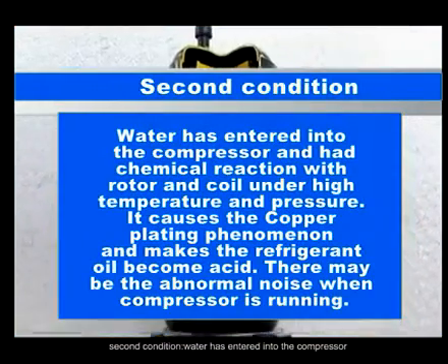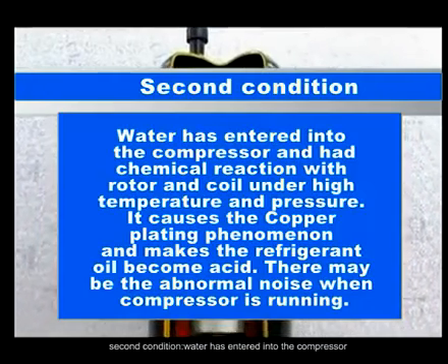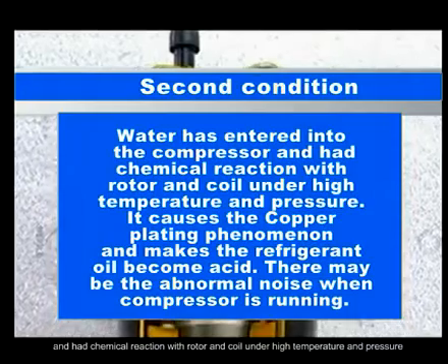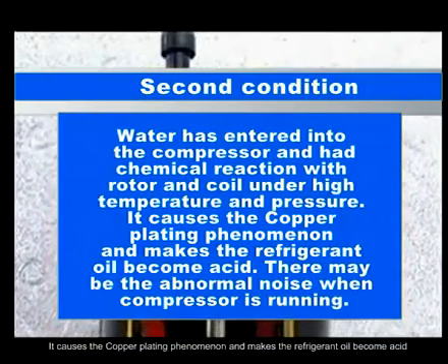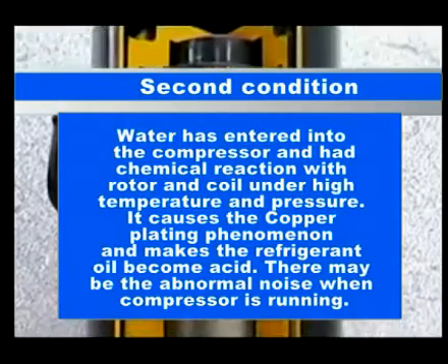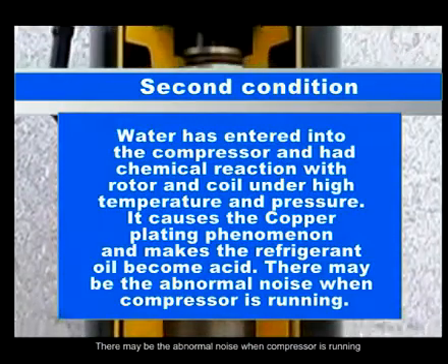Second condition. Water has entered into the compressor and had a chemical reaction with rotor and coil under high temperature and pressure. It causes the copper plating phenomenon and makes the refrigerant oil become acid. There may be abnormal noise when the compressor is running.